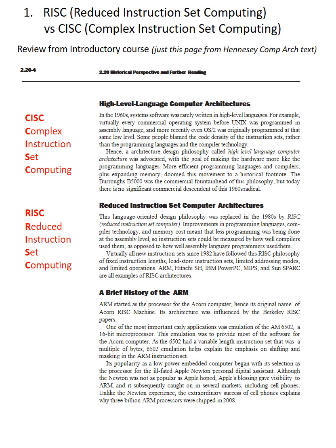There are other things that happen, the hardware control, or the hardwired control unit in the CPU, versus one programmed in nanocode. Don't want to get into that in this course. The control unit that controls the data flow, or the finite state machine that we discussed in 332 class, the Digital Design 1 class, we designed that, is hardwired instead of microprogrammed in the RISC.